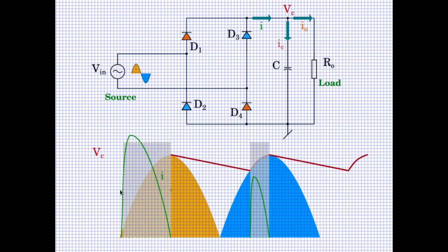What if at the time of turn on, the turn on was not synchronized with the zero of the input voltage, but it occurs somewhere here, which means the turn on occurs somewhere at this point, which means that the capacitor voltage is zero and the grid voltage is a pretty high value, and you are connecting two potential devices together.